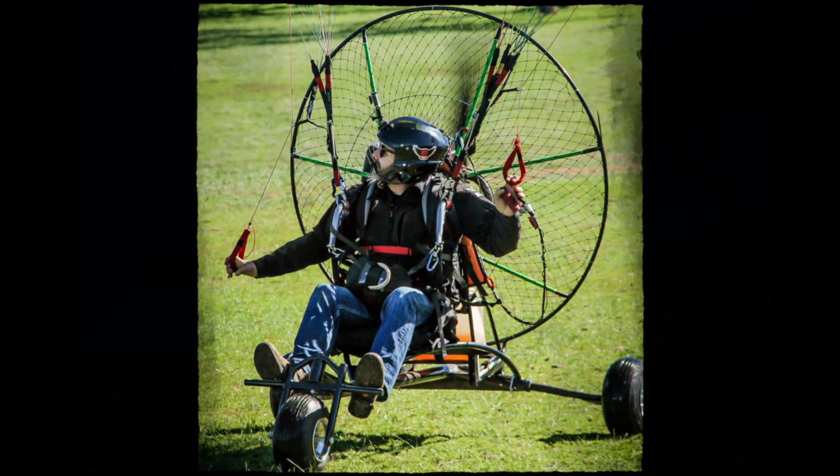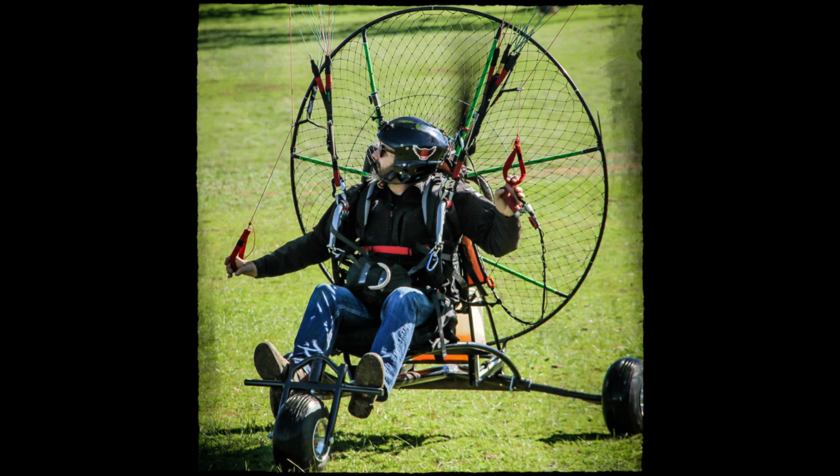The cylinder head temperature or coolant temperature must be up to the manufacturer's recommended temperatures before takeoff. This may require running the engine at higher RPM to reach required temperatures on some engines. Once the engine is warmed up and the aircraft is flying, it is still possible to cool down the engine too much. This happens when the engine is idled back for an extended period of time. Even though the engine is running, it is not generating as much heat as the cooling system is efficiently dumping engine heat into the atmosphere.